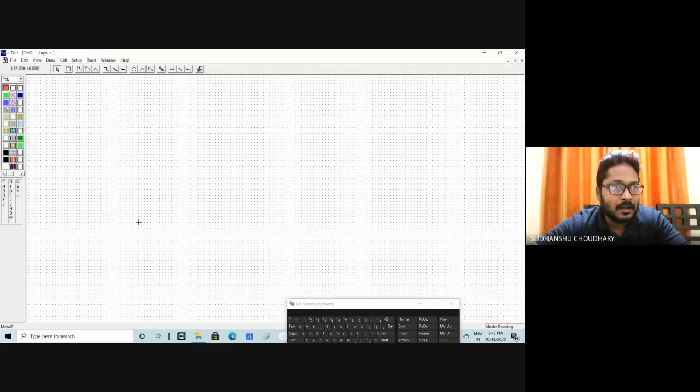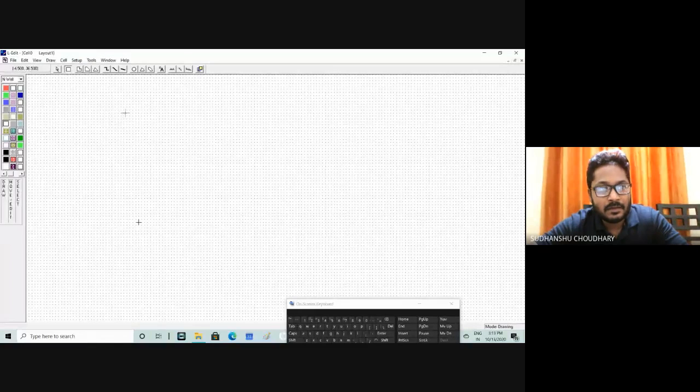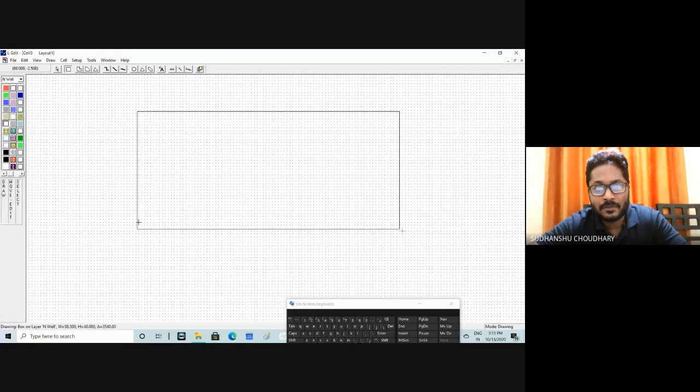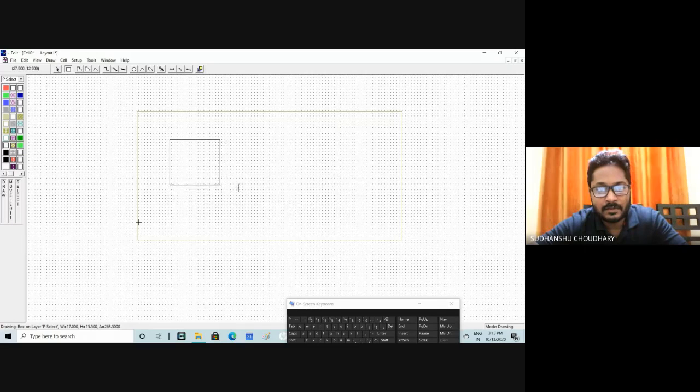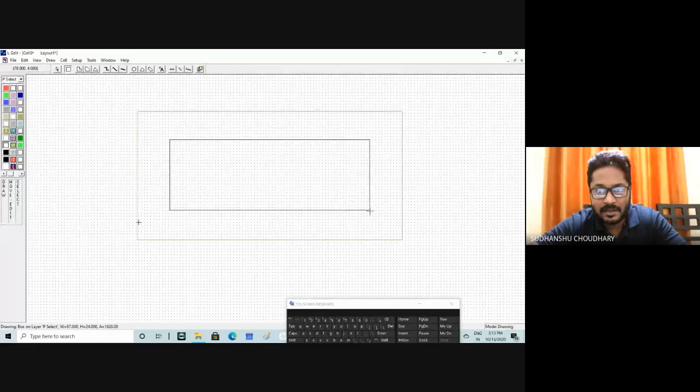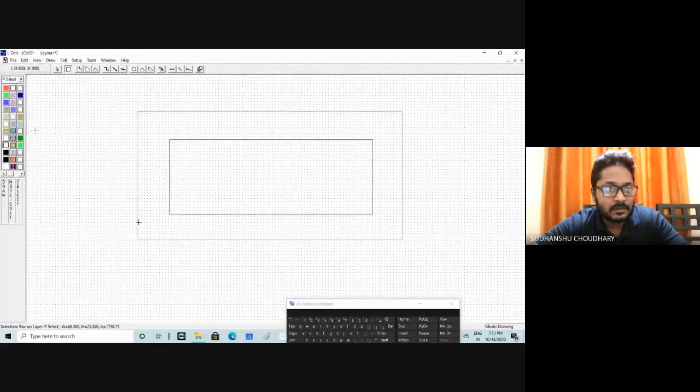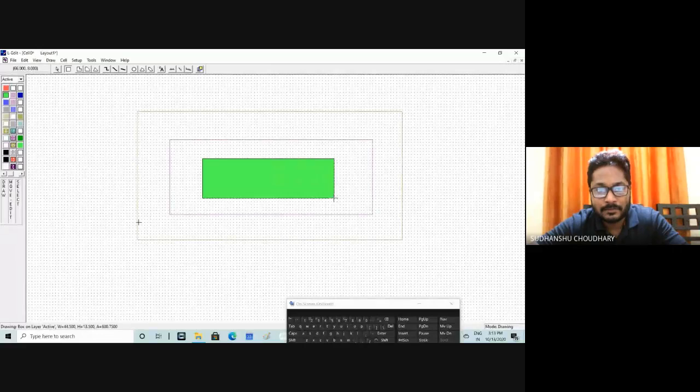So for PMOS, again we will select N-well. So I'll select N-well from here. This is N-well. I have drawn now N-well. Let us draw. So this is, let us say, my N-well. And then inside N-well I draw this P-select. So I select P-select and then this P-select, right? So I'm keeping the dimensions large, as I said, so that there are no DRC errors. Then in the P-select, I need an active. So I select this active and I have drawn this active now.